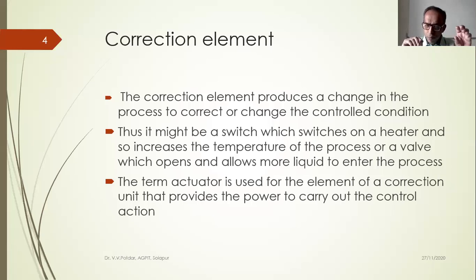I have once again one potentiometer which has got a dial, and I set the value, same calibration constant I'll be using. So 100 corresponding to 100 degrees Celsius, I'll be setting a voltage of 10 volt. Okay, for 100 degrees Celsius, it will be 1 volt. For 1000 degrees Celsius, it will be 10 volt. So for 1600 degrees Celsius, it will be 16 volt is the set value of my temperature. Now 16 volt corresponds to 1600 degrees Celsius inside the furnace.